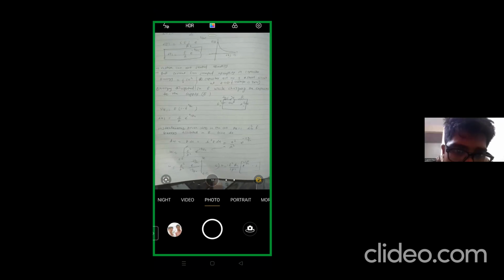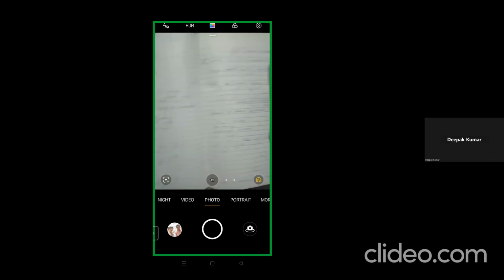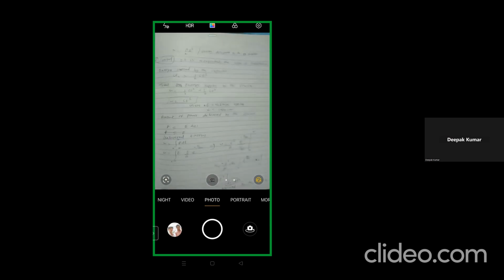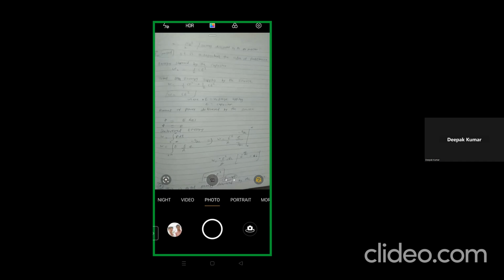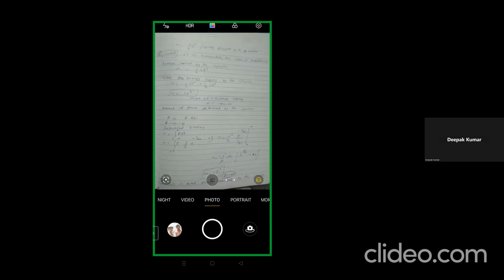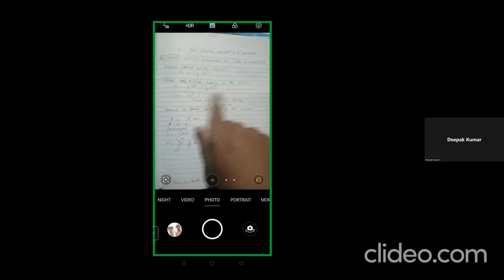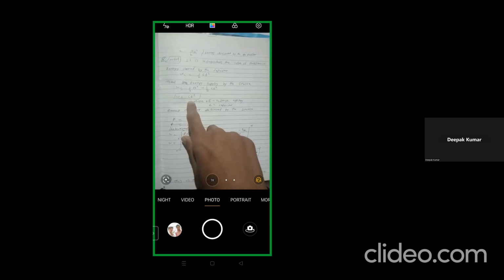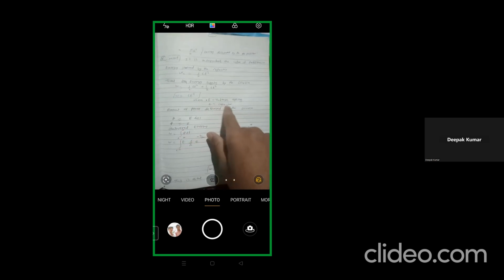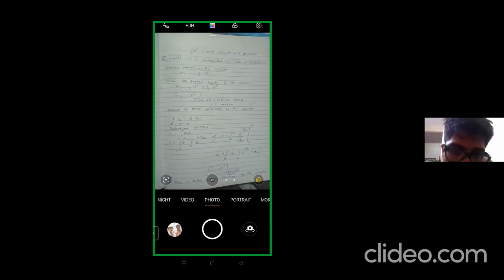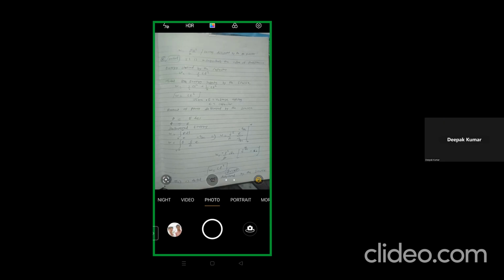Then you can say the energy dissipated by the resistor W equals 1/2 CE square. And the total energy supplied by the source W equals 1/2 CE square plus 1/2 CE square. Total W equals CE square, where E is the voltage applied and C is the capacitor. So that's why I am asking.